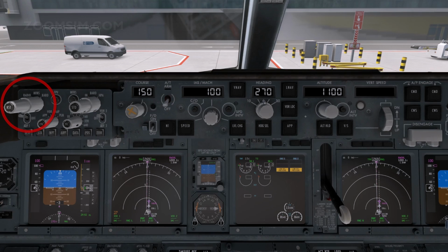Minimums reference: radio or baro. Minimums: set decision height or altitude reference. Flight path vector as required. When selected, flight path angle and drift are displayed. Meters as required. When selected, altitude is indicated in meters.